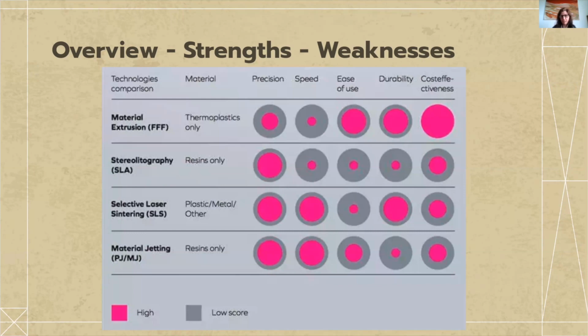And then you have the material jetting that I was talking about previously. It's also very high speed, very high precision. It is about cost effective. So the machines also cost about 250, 300,000. And as you use resins, the durability of the object is really not that good. So for example, you could make figurines that you put somewhere as a model to look at and never touch. So that's more or less what you can do. But they can use lots of different materials, maybe also in combinations. But mainly it's resin, and resin just hardens. Okay.